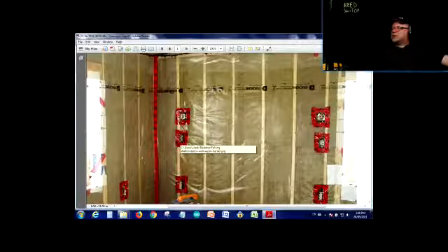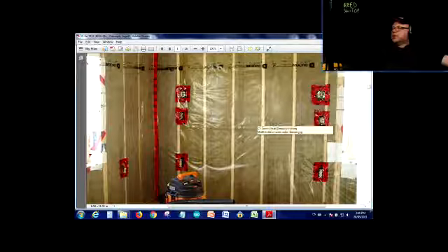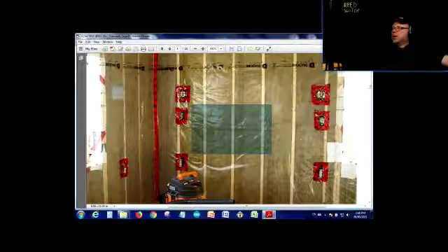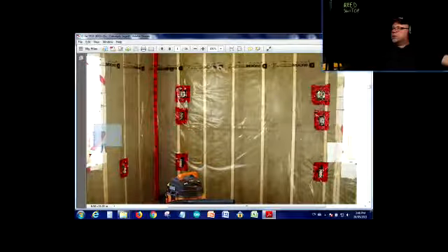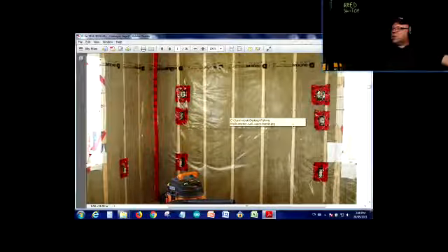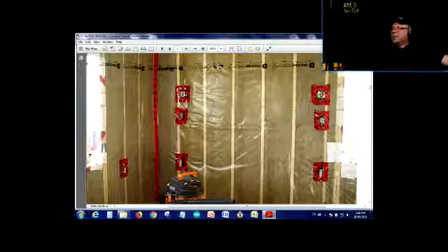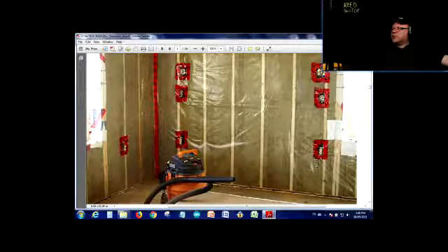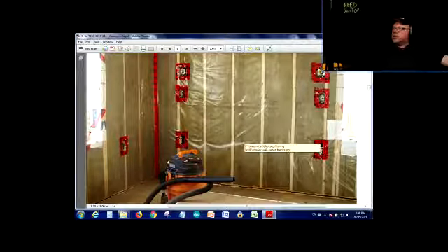All the outlets, all the switches, they should be sealed from the outside, because this is an outside wall and this is an outside wall. Obviously, you can actually see the window here and you can see a window here, right? So both of these walls are outside or exterior walls. And you're going to see that vapor barrier there. And then you're going to see some insulation. And on the other side, you're going to see a breathable barrier, all right? So it's not supposed to breathe as much from the inside, and it's supposed to be breathable from the outside. So there's some sort of gases exchange. Okay.